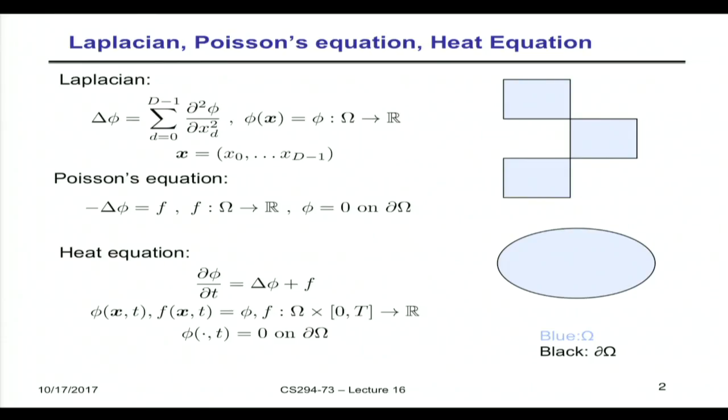I'm pretty sure Phil covered this already, but his dimensionless notation here, where you can express the Laplacian as a sum of each dimension's second-order derivative, and you're doing it on some domain that could be a nice union of rectangles or squares. You can do it on more complex domains. You might want to grid this with an unstructured mesh, or one of the approaches that I use is to do things called cut cells, where you overlay this on a regular Cartesian mesh and then fix up your discretizations around the boundaries.